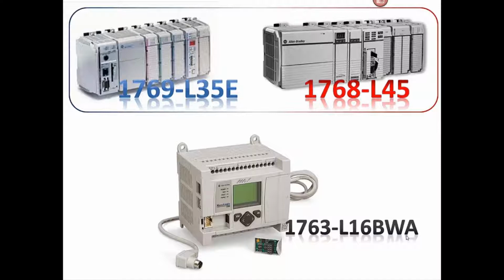All controllers the world over have at least one communications port. At the least, they have an RS-232 electrical interface, and then they don't all have the same protocol though. So RS-232 is not a protocol. It's an electrical specification, and it's usually represented with a 9-pin sub-D shell. And this connector will be somewhere on the controller. However, these are beginning to disappear from controllers in favor of USB 2.0 ports and/or Ethernet ports. I said all controllers the world over have at least one COM port. They can communicate with each other.